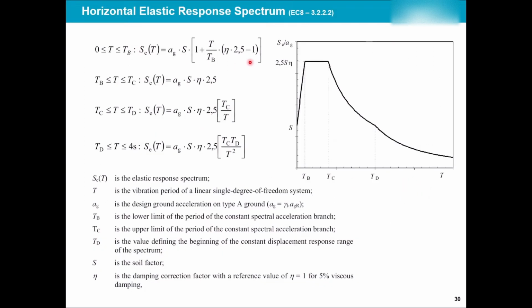These are the familiar formulations. Just remember that, looking at the title, the clause of Eurocode in which these formulations are given, or the future formulations are given, is always indicated over there, so you can refer to them. Again, remember, this is the horizontal elastic response spectrum. We have not talked about plasticity or any discount, just simply putting in the period of the structure, you're able to derive the response spectrum.